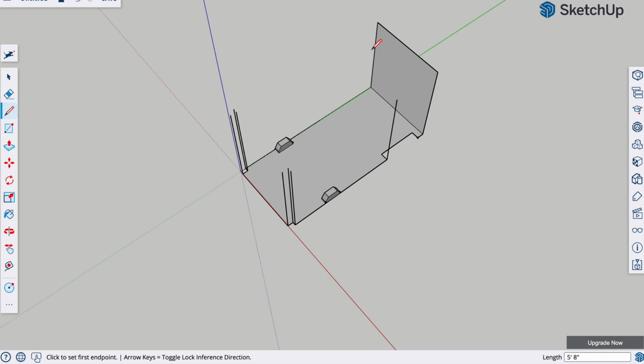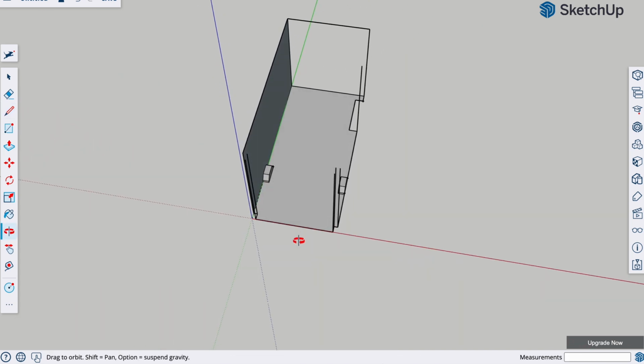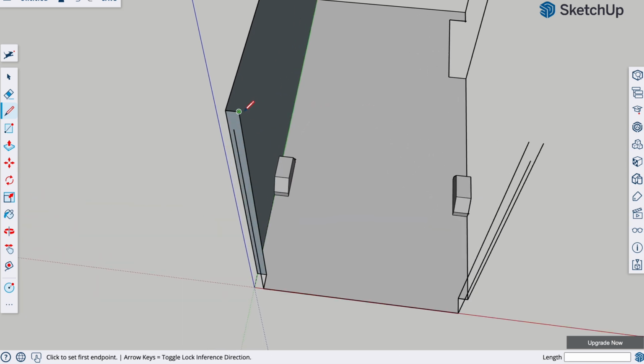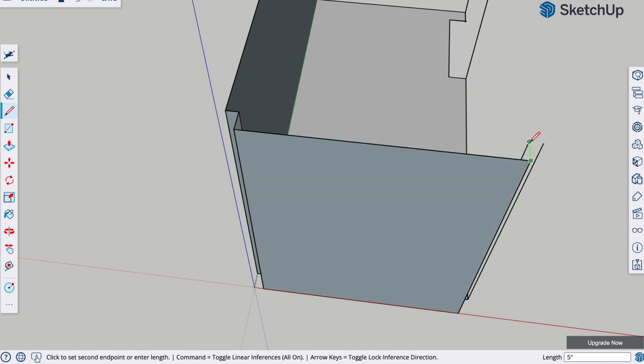So once this happens, the cabin of your van is going to be here, so obviously you don't want that. You can always just click on a face and hit delete. So you'll have the lines, but not the face, and you can decide whether you want to keep them or not. Let's see, we're going to connect all these. Boop, boop, boop. Zoom in a little bit. Perfect. Click, connect, connect, connect.